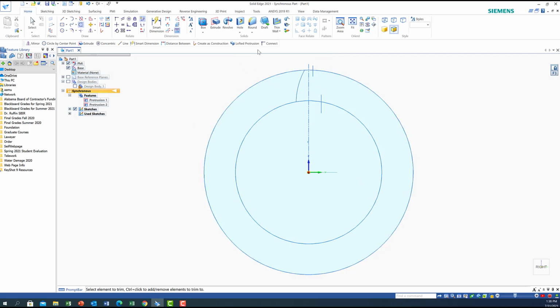Actually, I don't need this one. By using the line of symmetry, what I'm going to do is highlight the curve. So this curve here, very good. Then the line here, and make a mirror. So click mirror about this line. So now I got the other side, okay? This way, instead of going back and trying to draw the circles and so on, now escape, so this way I have it ready.